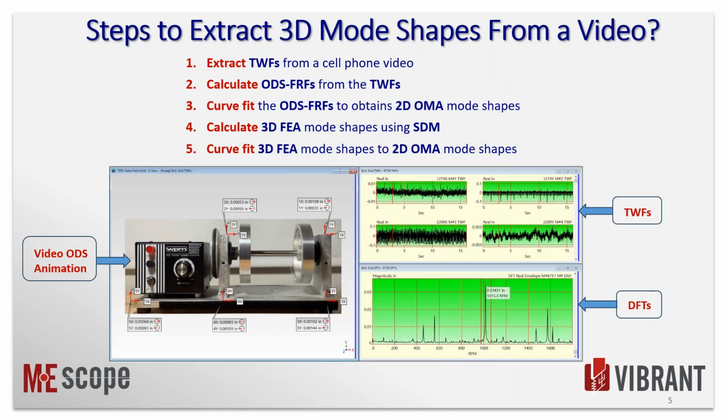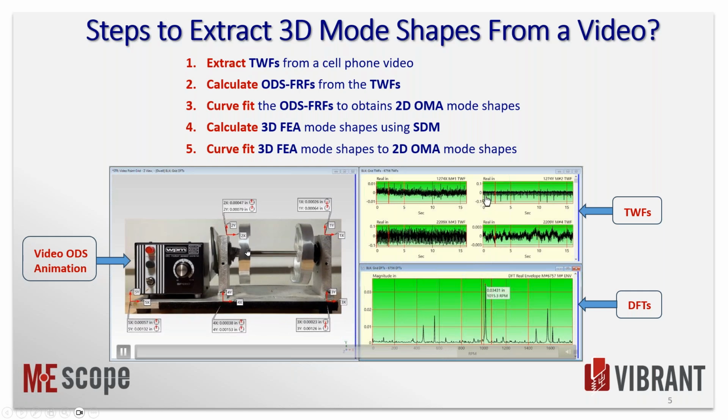But, you know, this animation here, you can't even get an animation like this. Now, granted, it's 2D as opposed to accelerometer data, which would be 3D, but you won't be able to see this otherwise. And if you look at this carefully, you're actually seeing the mode shapes of the rotors built into this. You know, all vibration is a summation of mode shapes.